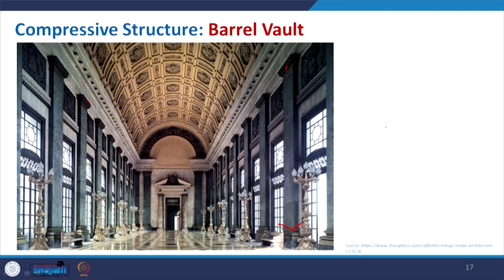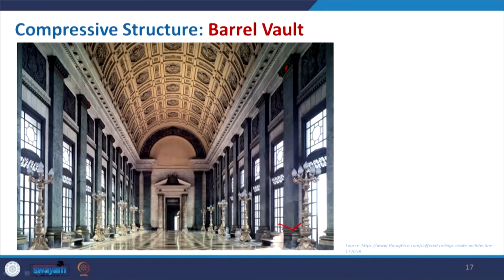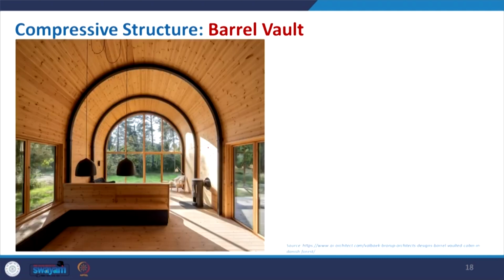We will also have a discussion on the vault section. One particular lecture will be on that aspect. Then we will see how different kinds of vaults act together, considering the compressive force, with most of the structural components dealing with compression. The barrel vault is one of them, an extended arch form that transfers the load to the support, where there is no tension, or maybe very minor tension somewhere where it is attached or closed.